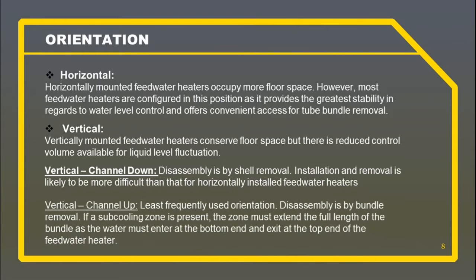Vertical channel up is the least frequently used type of feedwater heater. This assembly is by bundle removal. If a sub-cooling zone is present, the zone must extend the full length of the bundle, as the water must enter at the bottom end and exit at the top end of the feedwater heater.